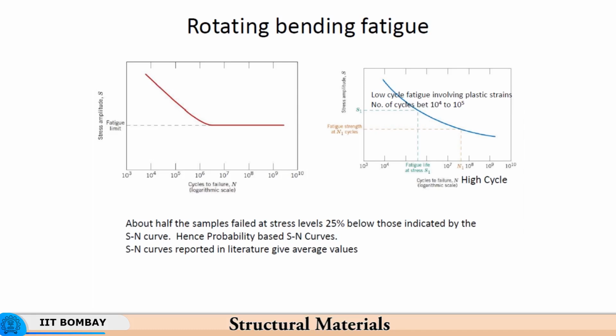That is because now the stress being high, the strain energy is high, and therefore the fatigue damage that gets accumulated also is high. Another feature of fatigue is that some Bauschinger effect comes into play, in the sense that when you subject a material to tension and compression, there is softening of the material. What softening means is that